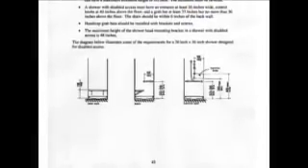And that's to prevent burns. Showers, go ahead and read the bullets, study the diagram, and note the dimensions. 1/2 inch in that first bullet, 36 inches, so on and so forth. Study the diagrams at the bottom of the page, and let's go on to page 24.